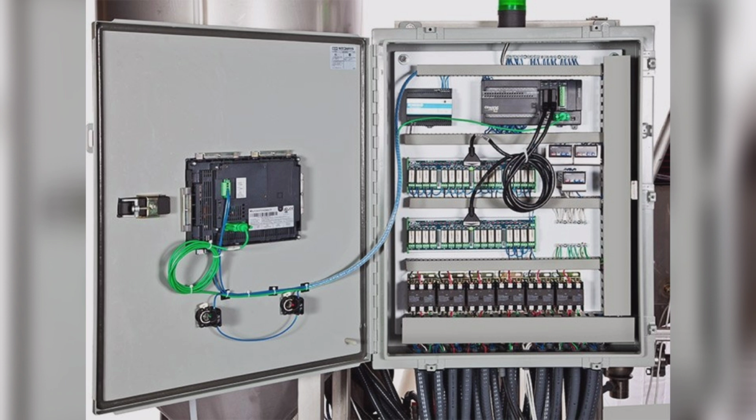Okay, then next, what is a terminal block? The terminal block consists of two terminals that can join two or more wires together. The terminal blocks can be arranged with several other blocks in a strip mounted on the DIN rail. The DIN rail is mounted on the chassis of the cabinet. It is not directly mounted on the cabinet or box. We can say there is a chassis, and the components are mounted with the help of the DIN rail to run the power from one source to several devices through the panel.